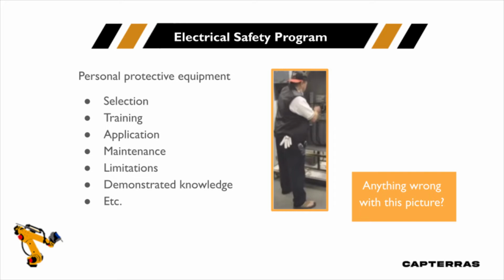It's absolutely critical that we properly maintain our PPE. I can't tell you how many sites I go to do an audit, and I find that people have a certain type of PPE, a treated fabric, and are taking home the fabric and laundering it without paying any attention to the types of detergent that need to be used. So in essence, in many sites, they're laundering out their treatment and not knowing that it's gone. So we've just, in essence, blown our PPE program right there with that one simple error.